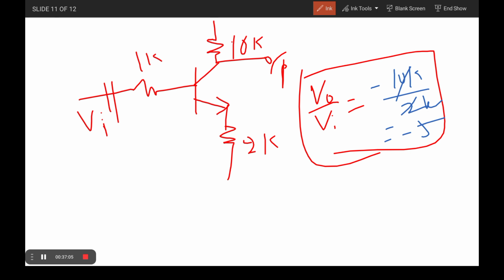The transistor is forward biased, so it acts as a resistor. On the output side, it behaves as a current source. Practically, there are small variations in the slope, due to which it represents a small resistive nature. Therefore, a resistance is connected in parallel to the current source. So this is all about the small signal model or RE model of a transistor.